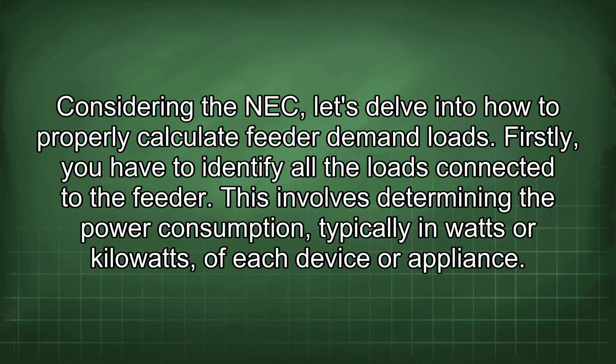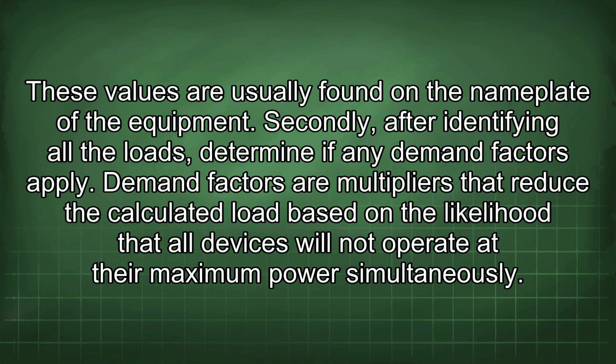Considering the NEC, let's delve into how to properly calculate feeder demand loads. Firstly, you have to identify all the loads connected to the feeder. This involves determining the power consumption, typically in watts or kilowatts, of each device or appliance. These values are usually found on the nameplate of the equipment.